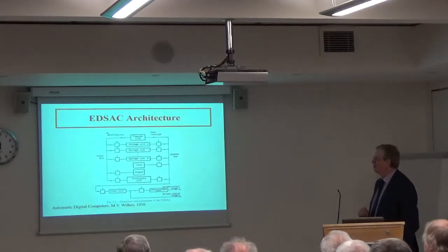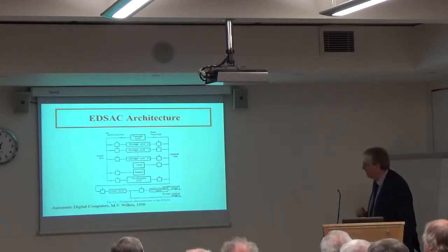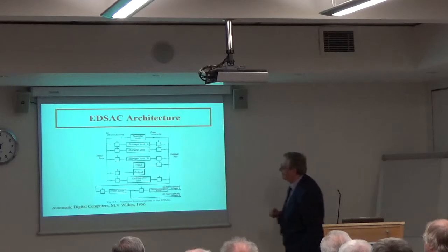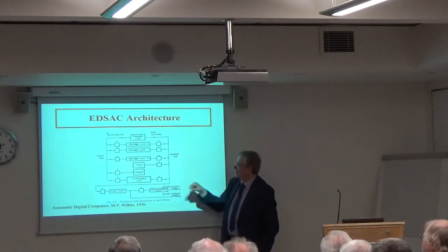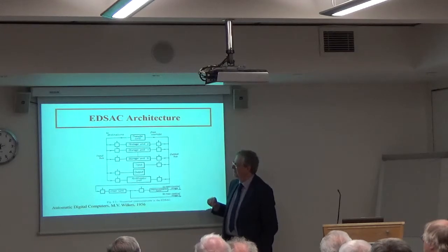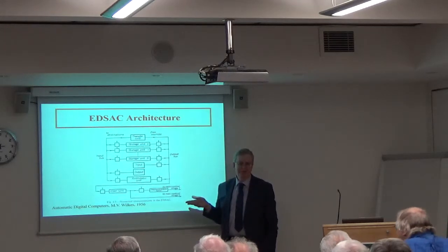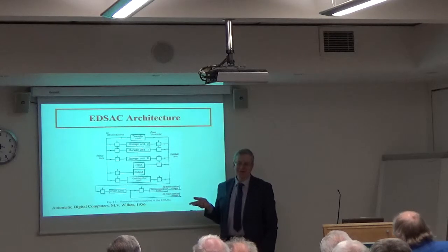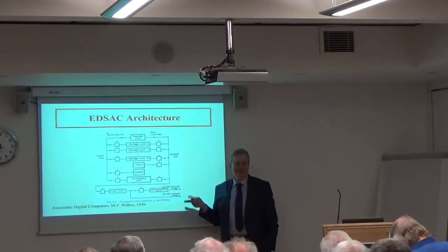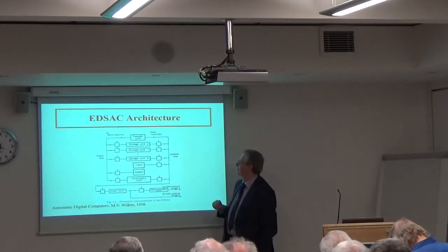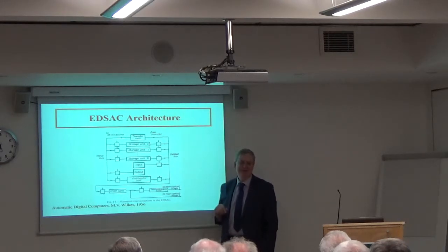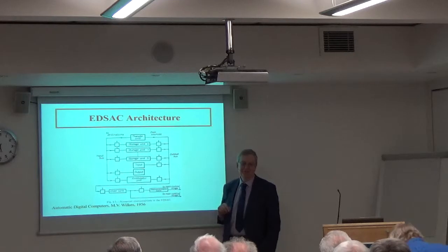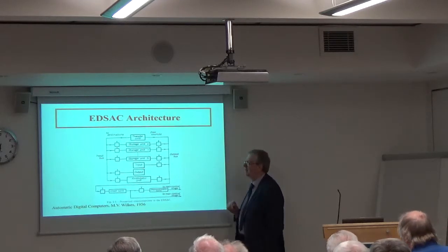EDSAC is a completely ordinary computer. It's a serial machine. The way you think about it is essentially there is a, although they call them buses, it's not a bus in a modern sense. That's another trap with old machines. They use language that sounds familiar, but it's subtly different. And so, although EDSAC has an input bus and an output bus, it certainly isn't tri-state. If you don't disconnect things or you put signals on at inappropriate moments, bad things happen.